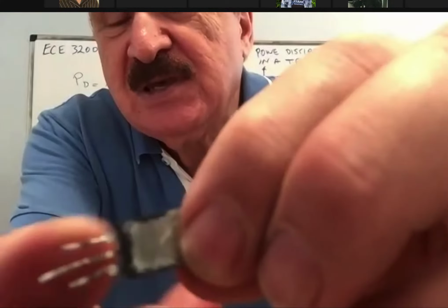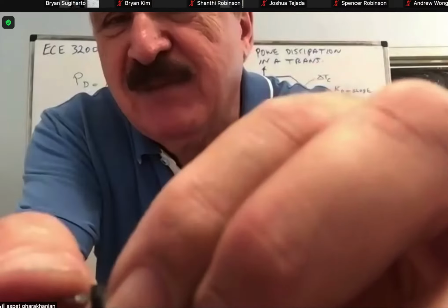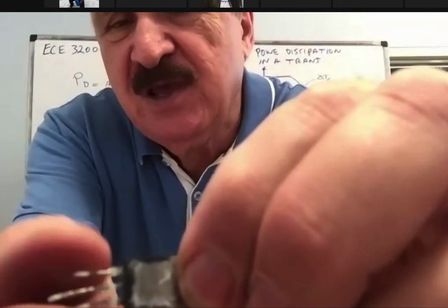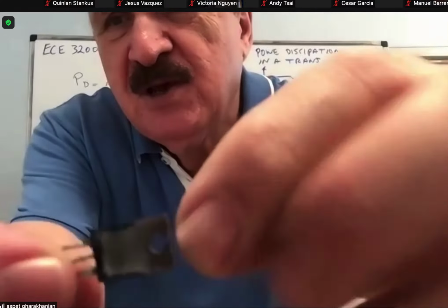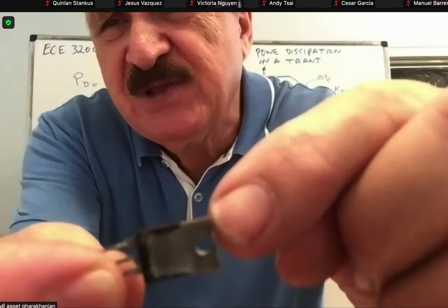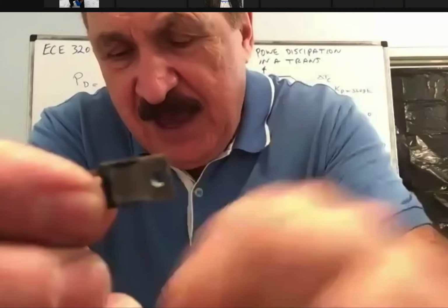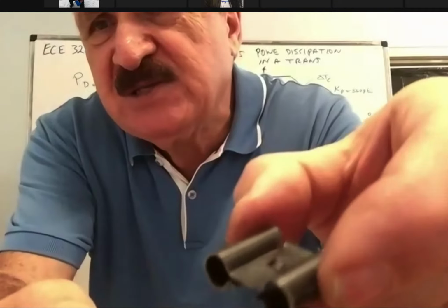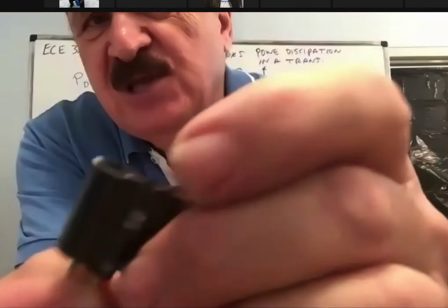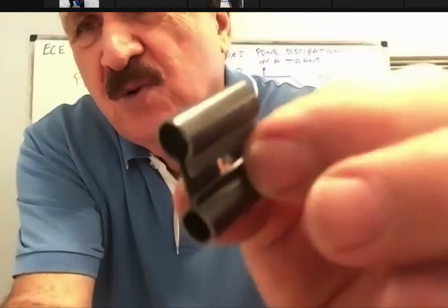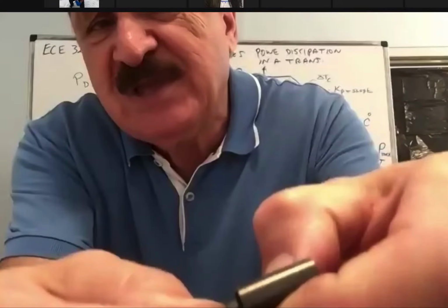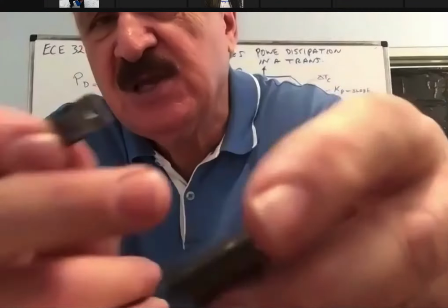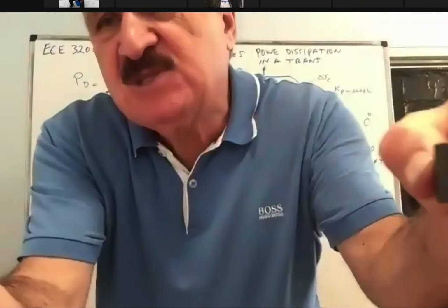which the semiconductor is attached to for heat conductivity. So as the junction heats, it transfers the heat to this metal stud that you can see with a hole in there. And then when you install that on a flat surface like that, right there in the middle of it, this additional area that you can see, this is a hollow, just metal basically. When you attach it there, the heat transfers from the stud into the metal and radiates into the air.